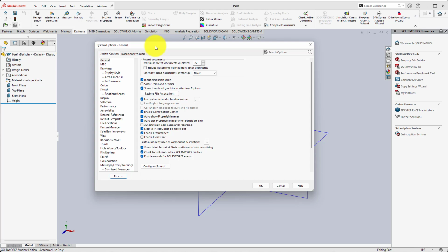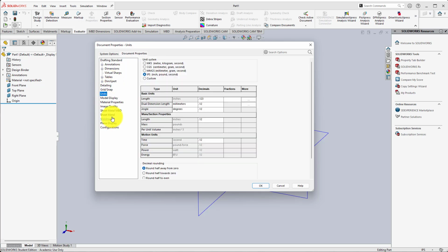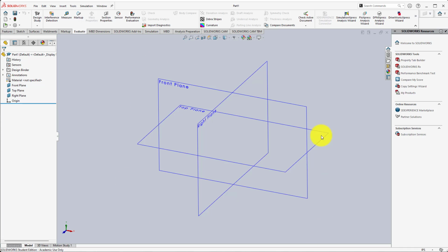And if you're leveraging the template that came with SolidWorks, pretty much the only thing that we're really going to change here in this course, because this isn't a full SolidWorks course at all, we just want to come in here and make sure that we're in ANSI drawing standard. Now mine says modified because when you click on this, you're probably going to be able to use the ANSI. And when you come down to units down here, you hit inch pounds, and I changed this to usually 3 decimal places right here on length. That's a real typical unit of length in the inch system we're going to have. It will put that as a modified ANSI, and that's okay. So we're going to accept those changes. That's the only thing I'm really doing in there.